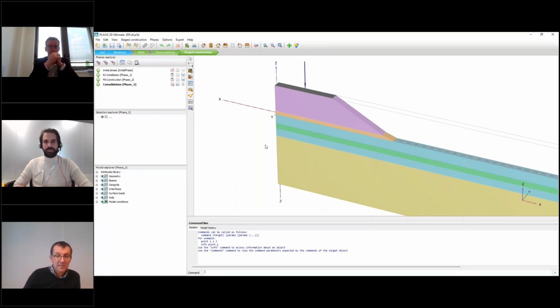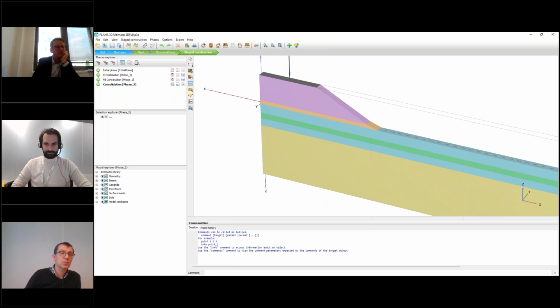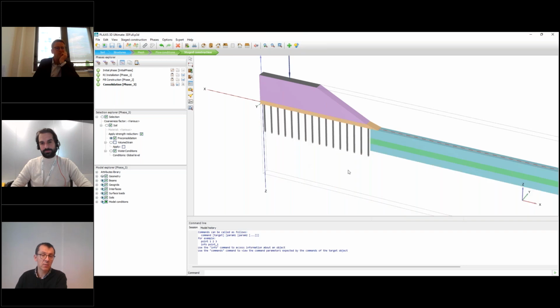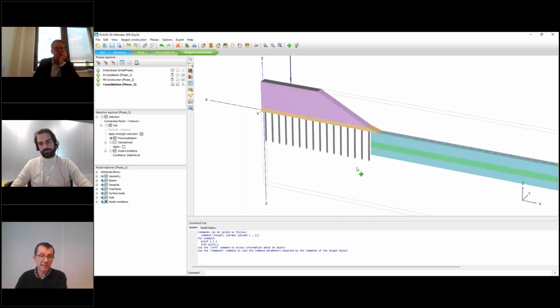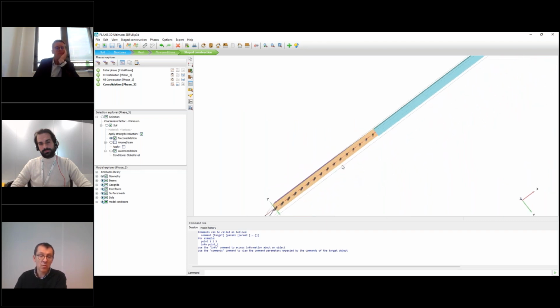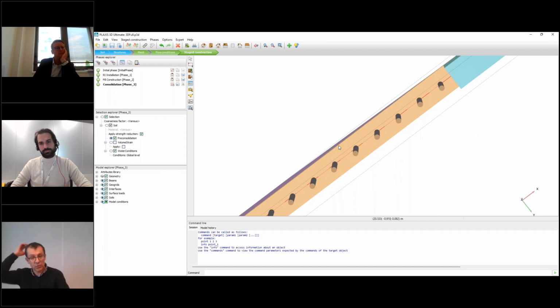Now, I decided to start very briefly, as an introduction, by presenting what these 3D slice models look like. That's indeed the best representation one can make for modeling rigid inclusion. Just to highlight my model, this is where the rigid inclusions are being placed. You see that spacing. You clearly see that they are right in the middle. So the model width here is exactly equal to the spacing between two consecutive rows of rigid inclusion, such that we can introduce a cyclic symmetry.